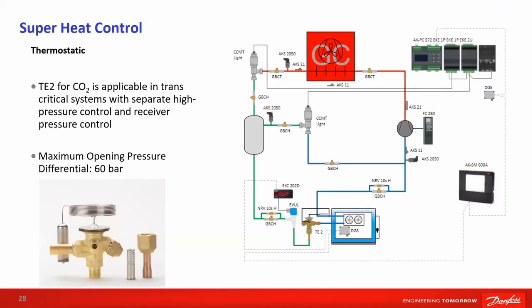So for this you must have an intermediate pressure. Even if it is electronic, it will be the same. For the evaporator efficiency also, it would be better to have the intermediate receiver. In conclusion, for the thermostatic expansion valve, the feed should always be liquid. Even for electronic, it is preferable to have 100% liquid, no gas bubbles. That is so for both types of expansion valve. Even electronic, we require liquid. I think it may work otherwise, but normally nobody does it this way.